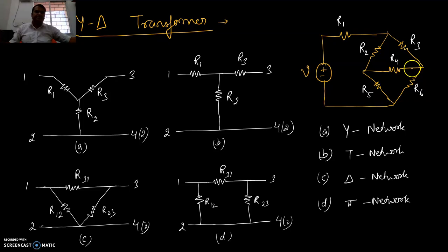You have another case where the resistors are arranged in this fashion, and that makes it a problem for us to find the equivalent resistance. If possible, I can redraw the resistances to look like this. Then it is possible that these two are in series and we have a two-branch network in parallel, and then we can relate these and find the equivalent resistance.